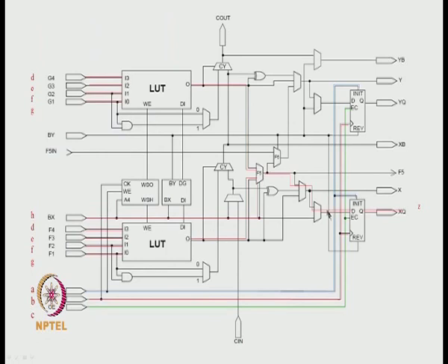So we have shown that you have taken this flip flop and we need 5-input lookup tables. So D, E, F, G go to the same 2 lookup tables. H is the 5th variable that selects this F5 mux. So that is combined, and that output is routed to the flip flop, and the flip flop gets the clock which is B, reset which is A, this blue line, and the clock enable which is EC, which is C. So that is how it gets mapped.